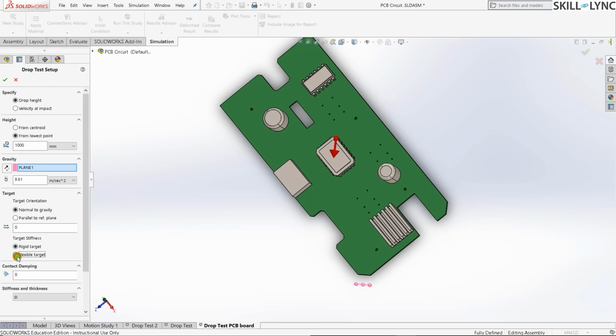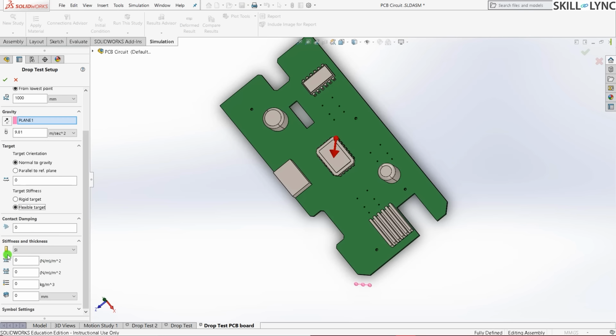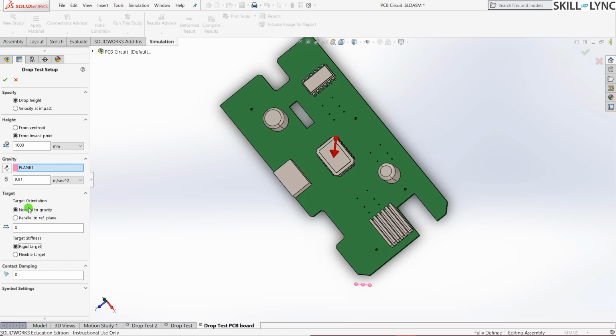Let's just go ahead and press that now. Here you can see that we have many more options. The first one would be the normal stiffness of the object, or the tangential stiffness, the mass density, the target thickness. By inputting these values, we can accurately shape the target as per our requirements. You can also change the units in which you want it to be. It's either SI, English IPS, or metric system. So we'll just select rigid target and proceed on with that.